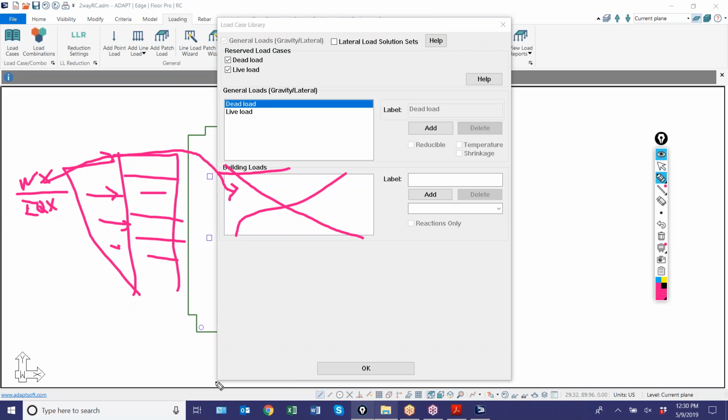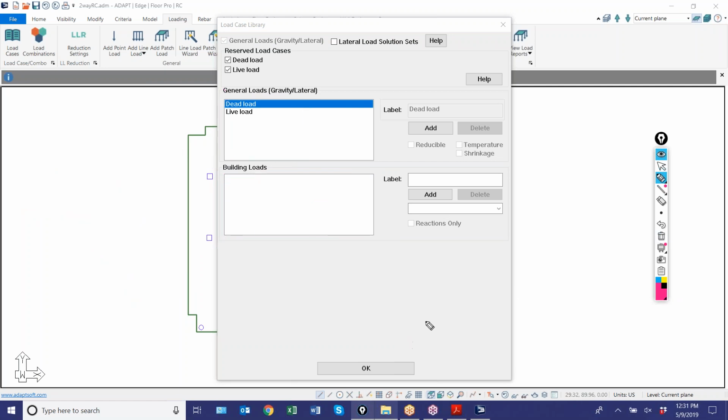So they don't really apply to a single level structure, because when you get lateral loads on a structure, usually, unless it's a construction lateral load for some special consideration, the building is in service and the load set would apply to the entire building, not just one independent level in terms of that particular model. So we're going to ignore this today. We'll come back and talk about that in a different webinar as part of our series here, but we're going to mainly focus on these 2 loads for the example.